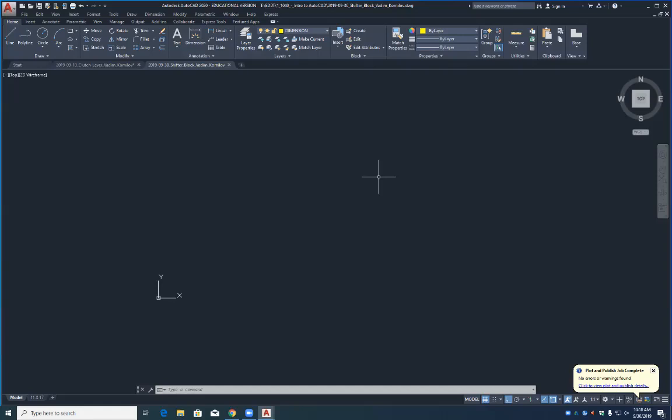Are you saying two hidden lines are overlapping? No. You have two parallel lines, and a hidden line going between the two lines, a 1/2 inch. That's an 1/8, that's an 1/8, that's an 1/8, that's a 16th, that's a 16th. The 16th and the 16th is an 1/8, so you have 4 eighths, which is a 1/2 inch, right? So that lets you know what a standard hidden line is built up of. Does that make sense? And so you can prove that to yourself on a drawing.